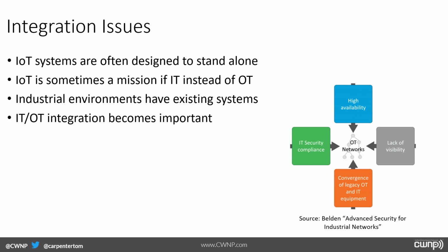So as long as the wire is connected, it works, kind of thing. And it's interesting because when you start to study some of these older wired OT protocols, a good example is HART. HART is a wired protocol often used in OT networks, and wireless HART is the wireless version of it. But the funny thing is, the actual speed of wireless HART is faster than most HART implementations. So it's wireless, but it's faster.